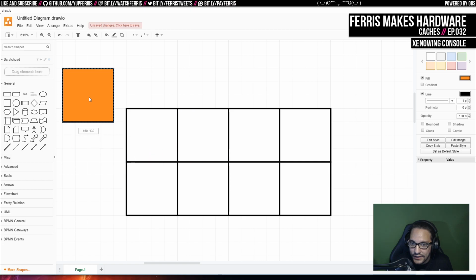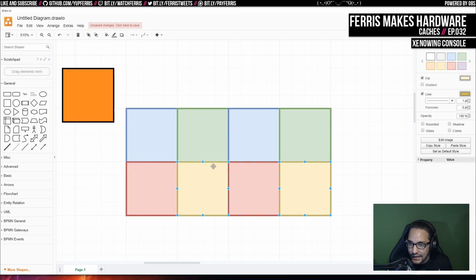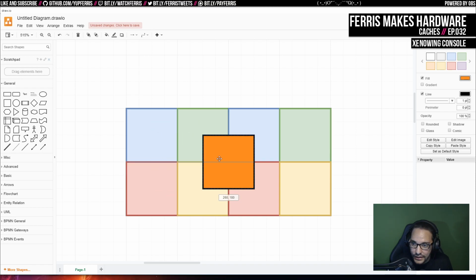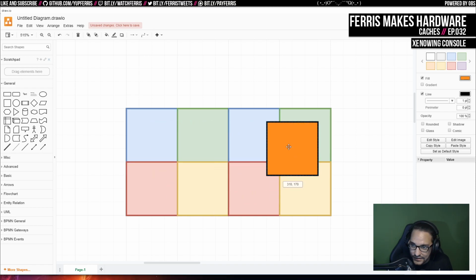But then, I interleave these into different segments in memory. So this is one, this is another memory, and this is another one. So again, I can read all these 1 per cycle. And the cool part here is, if I move this sampling point around, it only ever overlaps each color once.